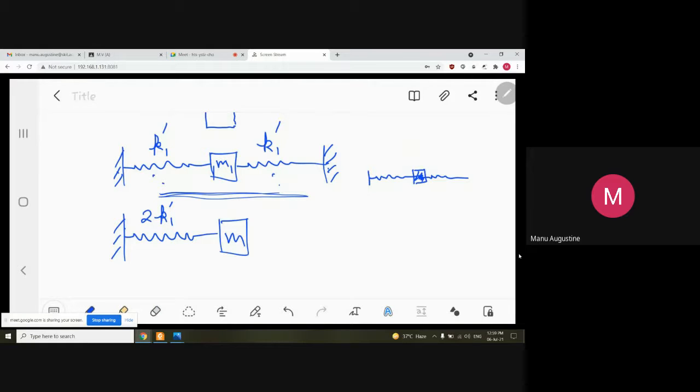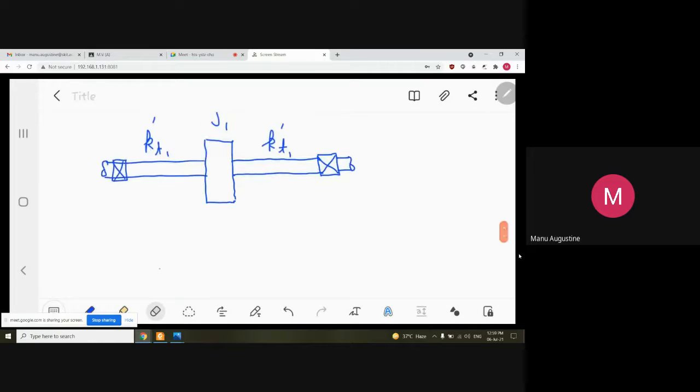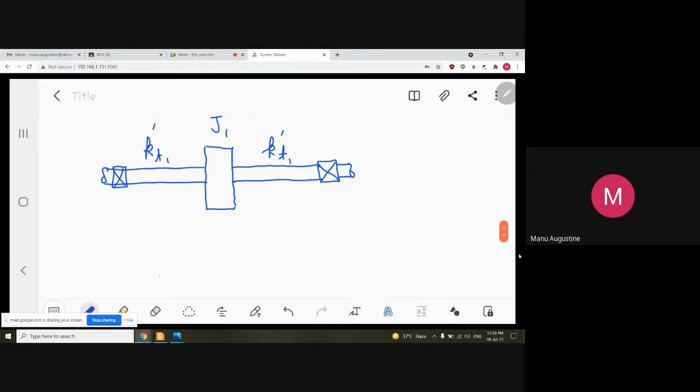Now we are not having a linear system. Actually, we are having a rotary system, and we draw a linear system to simplify things for us, because rotary systems, as a general matter of fact, are not convenient topics for most of the people. So that is why we take a more convenient route by selecting a linear system as an example. Now for the rotary system, if I make the similar conversion, just imagine that the shafts on both ends are acting as springs. And again, they are obviously in parallel because they are connected on either side of a centrally located rotor.